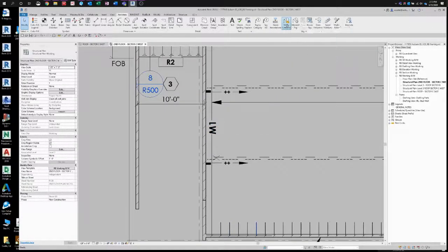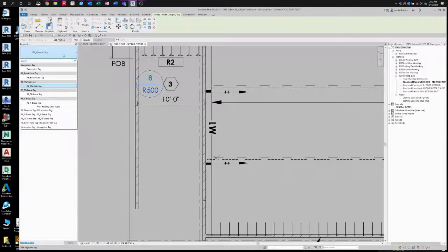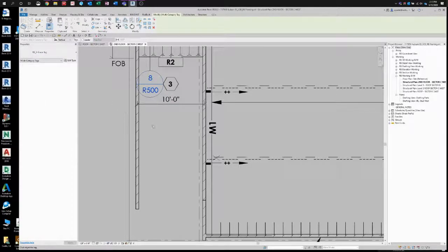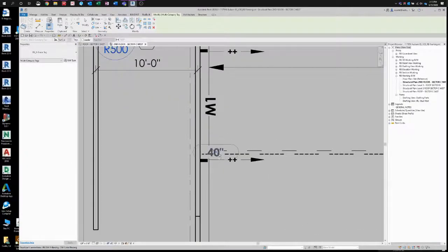The next multi-category tag we can do is in the type selector. You can come through and there's multiple description tag, bevel plate, the member tag that we just did, TV bracing, or cross bracing for open web. We'll select this one. In here, you float into where your cross bracing is. And here, we're going to want to make this horizontal and have a leader set for it.